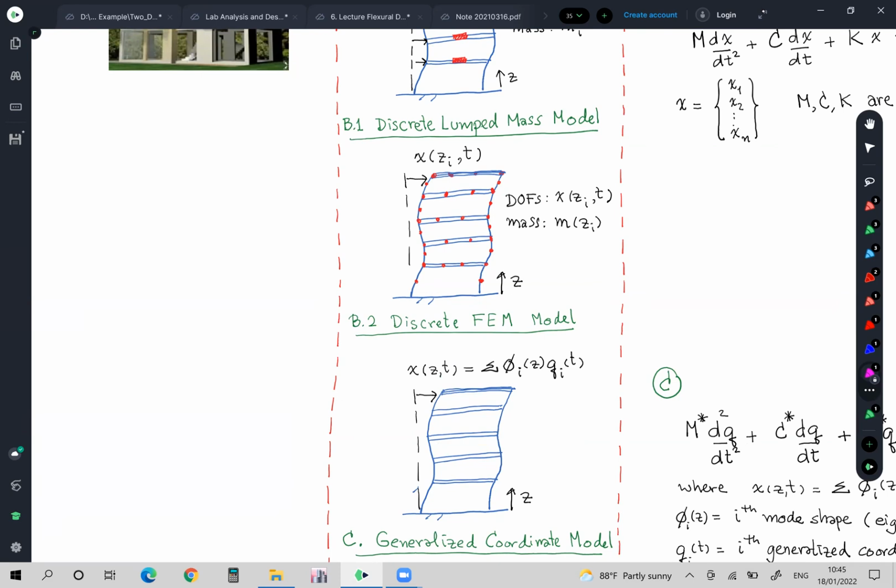Like in the building, we try to build up this model by adding elements of columns, elements of beams, elements of slabs, elements of shear core, something like this, right? So you build up the building in this finite element model by using a large number of elements.